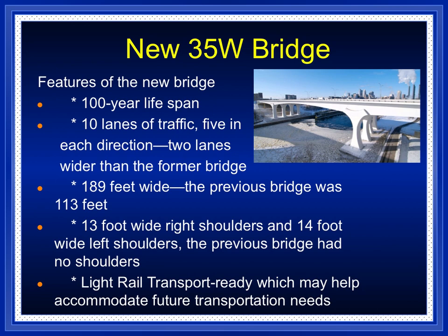Features of the new bridge or redesign include a 100-year lifespan, 10 lanes of traffic, 5 in each direction, 2 lanes wider than the former bridge, 189 feet wide. The previous bridge was 113 feet. 13-foot wide right shoulders and 14-foot wide left shoulders. The previous bridge had no shoulders. Light rail transport ready, which may help accommodate future transportation needs. These were all part of the redesign in the new bridge that was constructed.